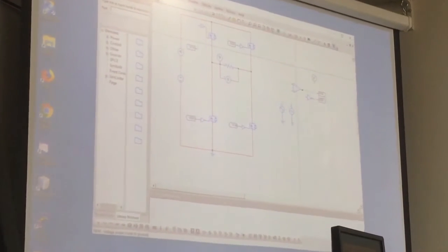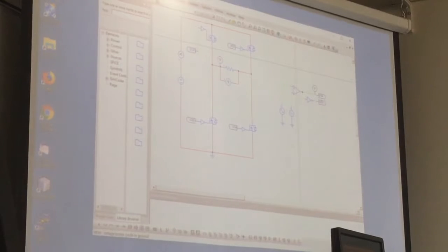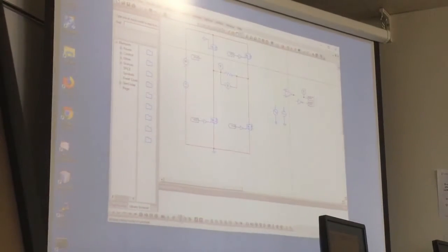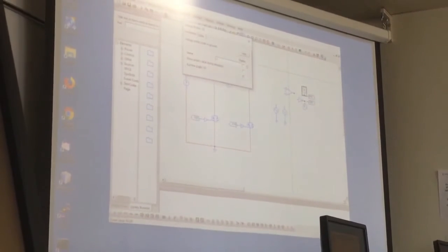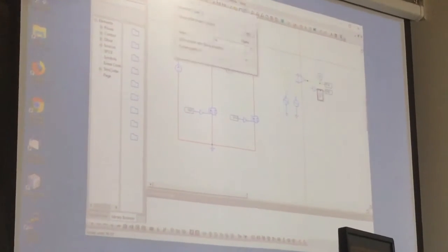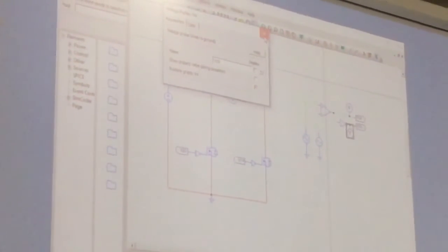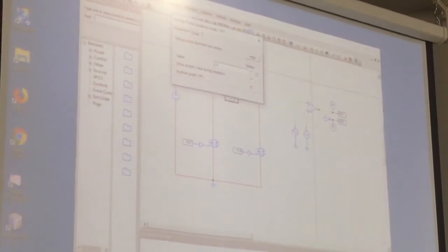And here I'll place 2 probes because I want to see the signals that I'm getting from my converter, okay? So let's say there's something wrong, it's not working, I can try to find the problem. So let's put some probes here. This probe here, we're going to call V14. This one, we're going to call V22. And for this one, I forgot to do, we are going to use V low.